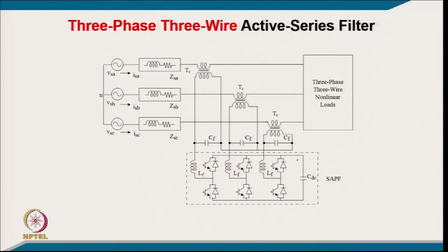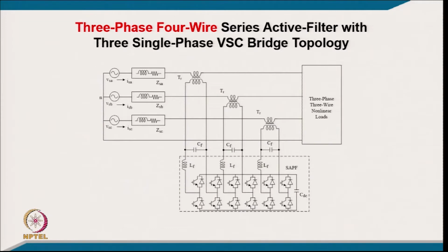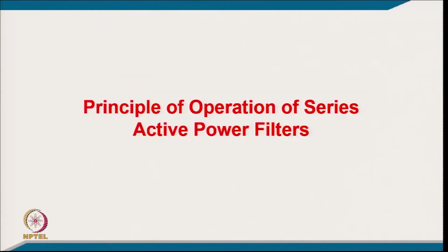So, it can typically improve the current harmonics in a voltage fed load, and in a current fed load it typically compensates the voltage also. So it is versatile, with more applications. And then this you can call 3 phase 4 wire. So, you have 3 independent legs here and you are connecting them in series. So automatically, if you are compensating the neutral harmonic current, the neutral current will be mitigated. Maybe you have a 3 phase 4 wire kind of load, or otherwise you are doing voltage based compensation. So, this is for 3 phase 4 wire.